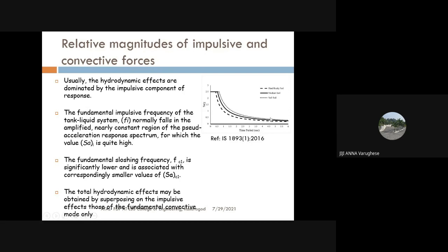And the first mode may come around this region, and the higher modes will have very little influence on the response of the water tank. So while designing a water tank, we combine the effects of the impulsive mode as well as the first or the fundamental mode effect.